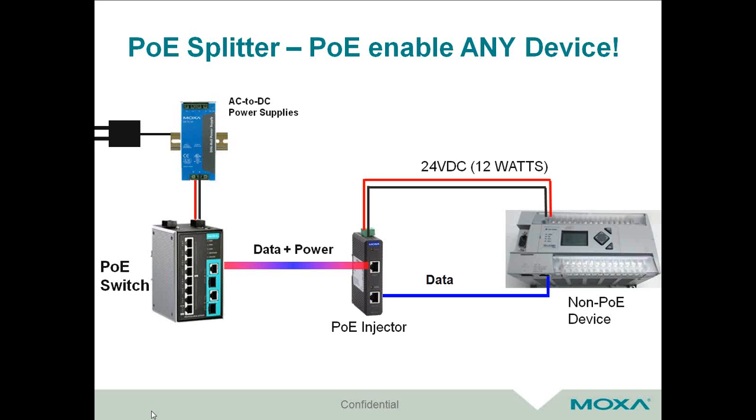You can choose to upgrade each side of the equation, whether you're upgrading your PSEs or your PDs, or you can do them both together with just a PD connected to a PSE. Or in other words, a PoE switch connected to a PoE device is your best solution. But sometimes it's not cost effective to do it that way. So here's another way to look at it.